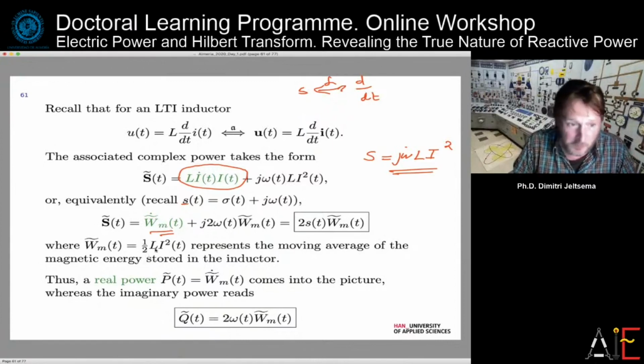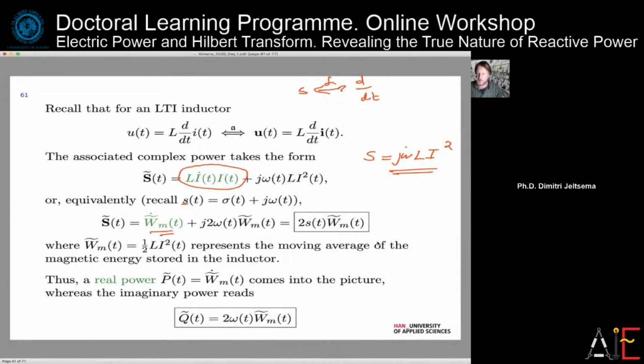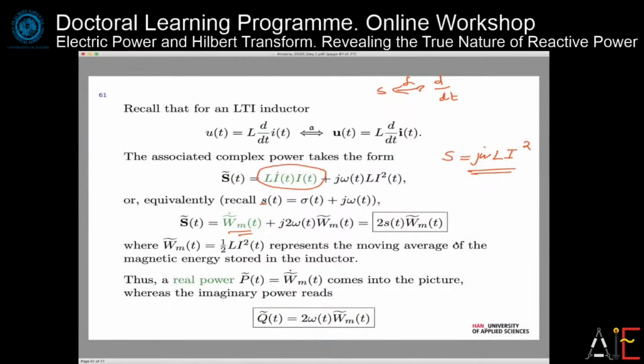Okay, and of course also, the charge and discharge of your inductor must come from real energy anyway. And I come back to that on Wednesday, because something weird with the classical notion of reactive power is that it functions like a perpetuum mobile or something. I mean, that oscillation is there forever. That cannot be true, right? But with non-sinusoidal signals, that appears already. You're already warned that some of the change must come from real energy, and that's dictated, or implied, over here, I should say.